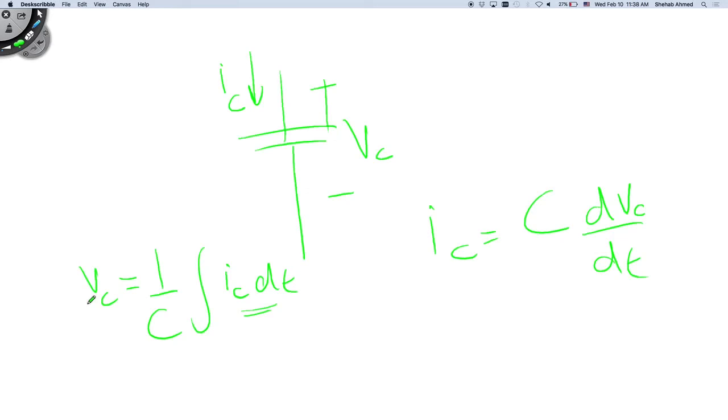If you try to change the voltage across the capacitor instantaneously, what does that imply? It implies a huge dV, a step dV in no time. That means I have infinite current. There's no such thing as that. You do not want that to happen. Sure, this can happen if you have a source that can supply infinite current, but of course, this is not practical. So typically, capacitor voltage rises gradually because our sources are current limited.